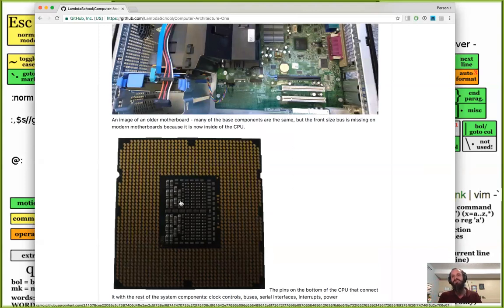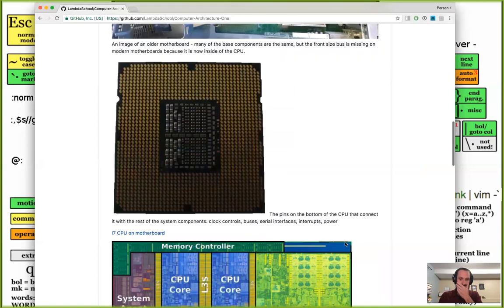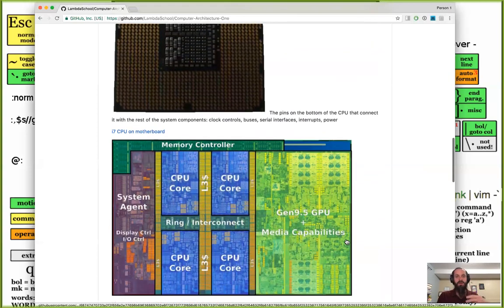And I don't remember exactly what voltage they need to be. When I was a hardware geek, it was something like 1.85 volts. And all of these capacitors, and probably like 400 of these wires, are dedicated to providing power to the CPU and then smoothing it out so that the power that goes into that 64-bit bus on the CPU is very, very steady and very, very predictable. Okay, now this next diagram is interesting. As for the other 500 pins, I don't know what they're for. They're for power regulation. They're for communicating with the different components that the CPU knows about. But they're all going to happen over a 64-bit word, essentially.